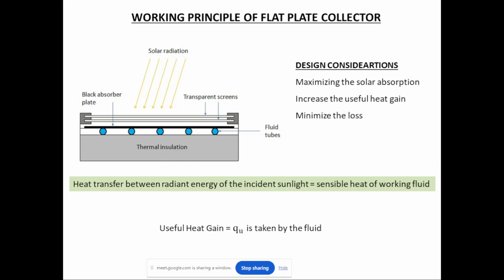So that is the reason why I encourage everybody at the initial stage to work out more on finding the value of IT as a function of month, day, time, theta, and phi, the orientation, so that you can observe what the maximum amount of solar radiation is that you can absorb.